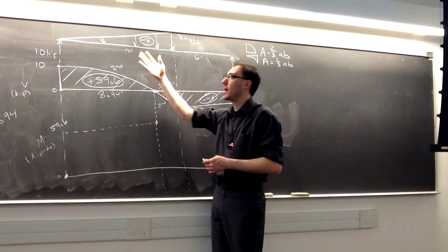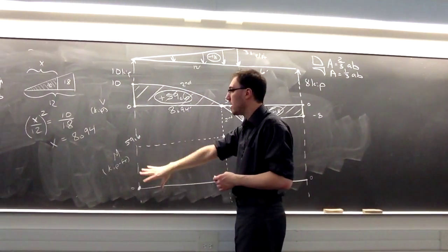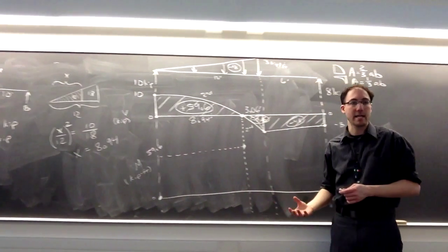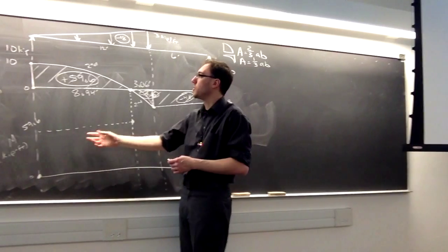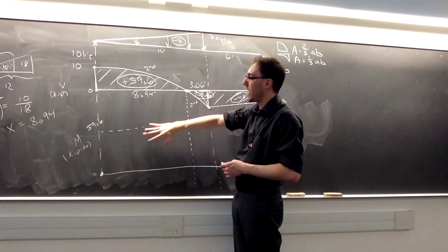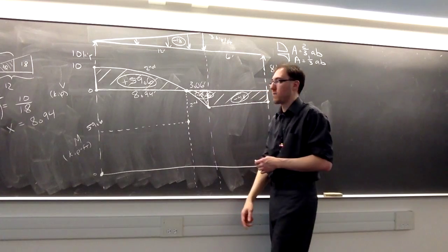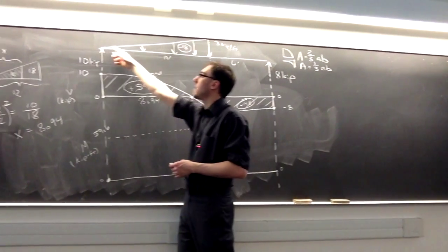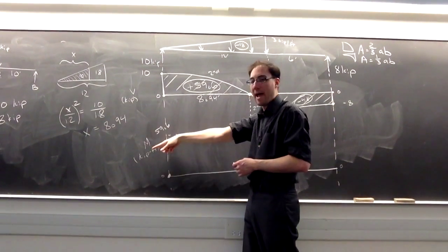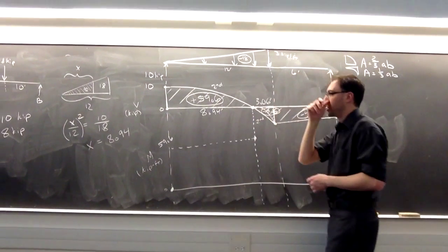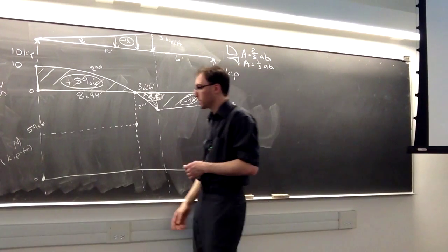Now, for second order, it's not too bad to assume we can at least get the concavity of it. For M, we're going to use basically the same technique and assume that there's not going to be an inflection point. Really, we don't have to assume that, because for an inflection point, the second derivative would have to be equal to 0. In this case, because the loading is the second derivative of M and it is not equal to 0, there will not be an inflection point. So we can treat it similarly to how we did second-order curves.